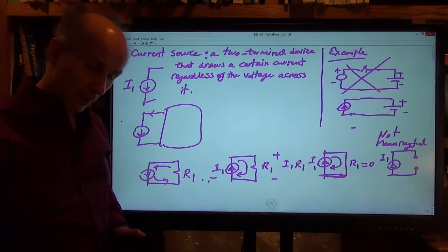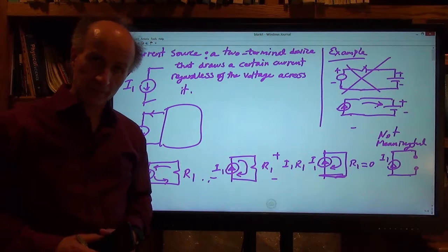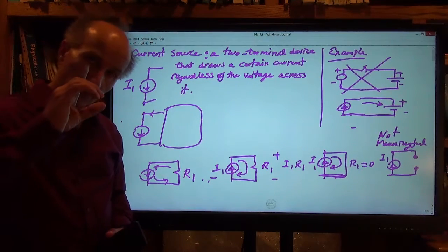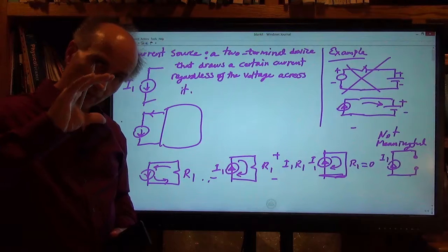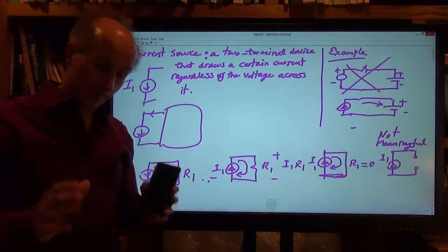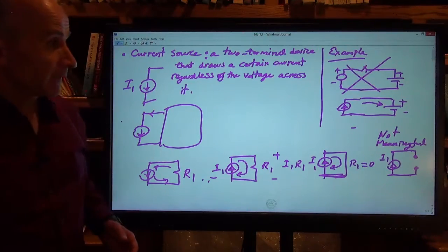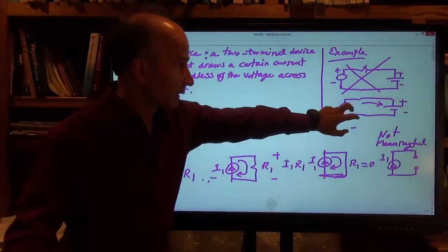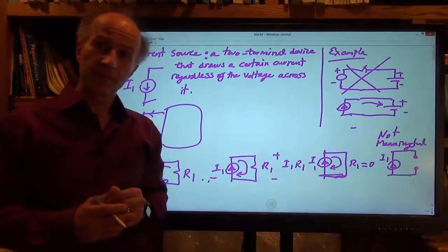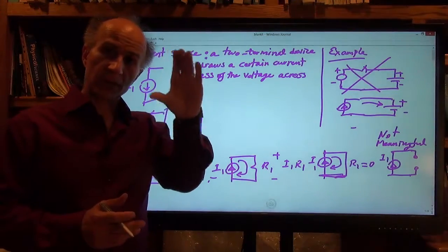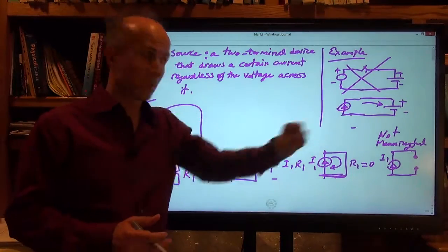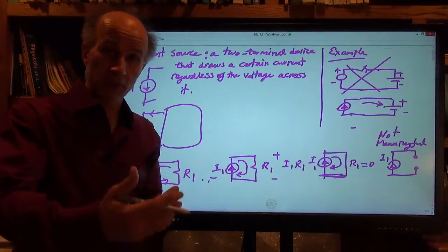And when that current is turned on, we keep injecting a certain current into the battery, and the voltage across the battery gradually goes up as it charges. And when it's charged up completely, we stop the flow of the current. So, in fact, inside the cell phone, there's a mechanism. It measures the voltage across the battery, and once that voltage reaches a certain threshold, it turns off this current source so that we don't overcharge the battery and damage it.